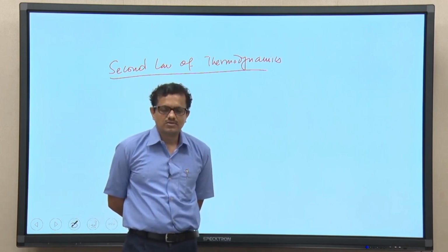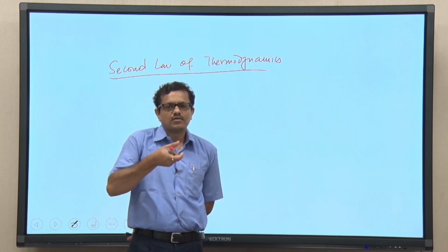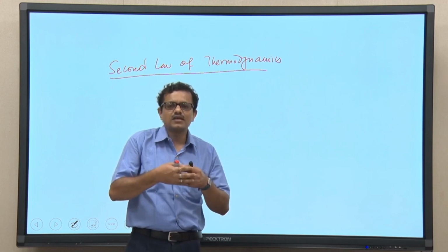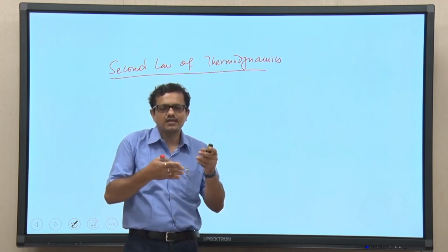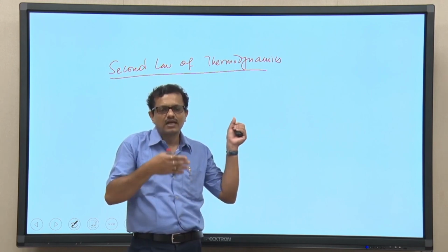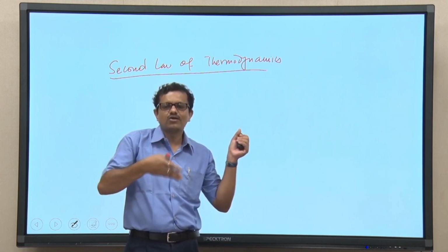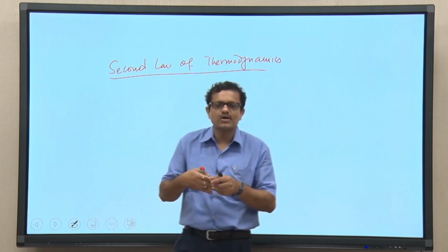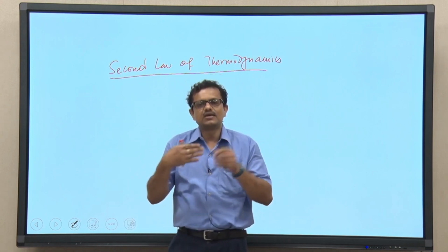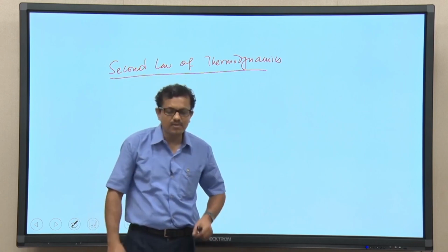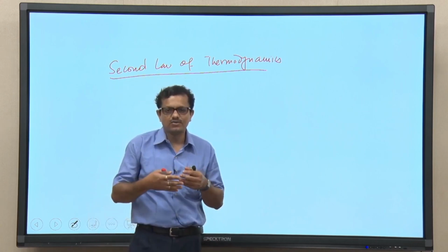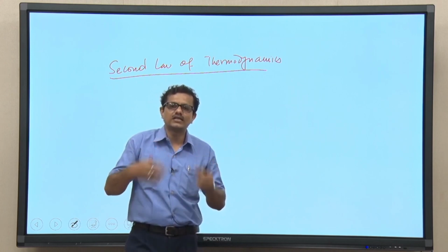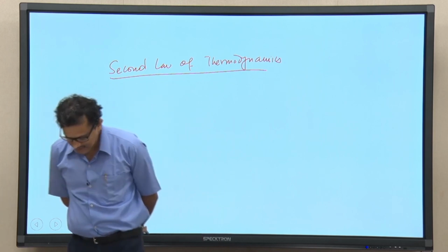the second law is used. So basically, if we have a compressor or a turbine, whenever the working substance is allowed to pass, as I was talking about, that is a flow process, not a non-flow process. When there is a flow process, whether it is occurring in a compressor, a turbine or a pump, we need to measure and assess the performance. So the second law is used to measure or assess the performance of thermodynamic processes.